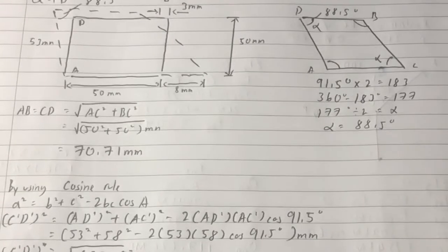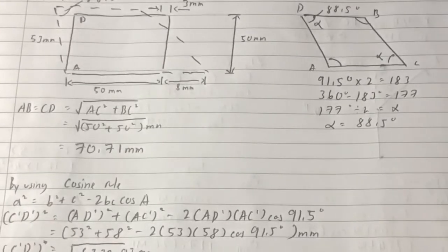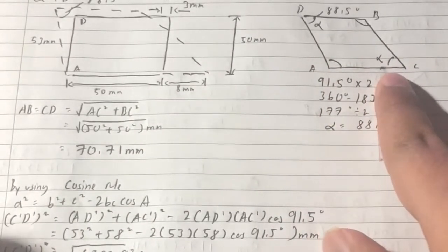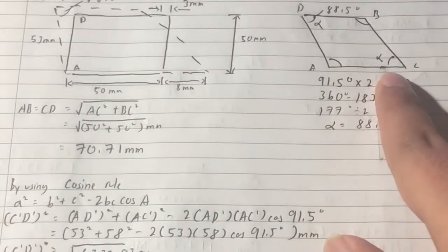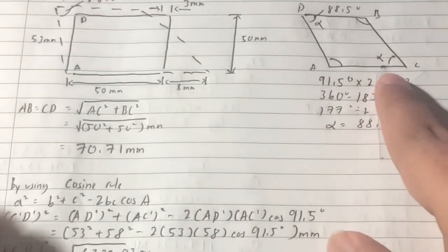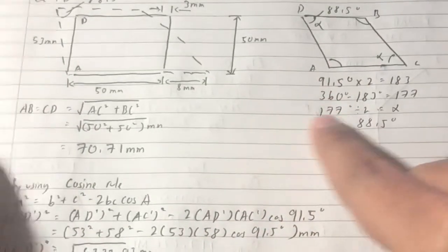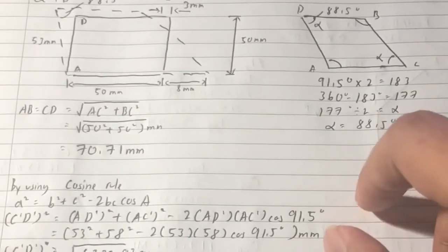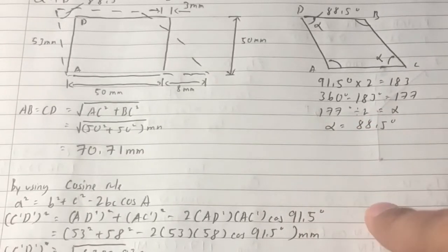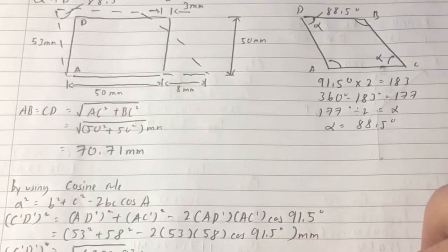So here we must first find CD, BD and AB, and when you have found all the lengths, we can find the average normal strain of each of them. So here is the solution to find CD, BD and AB.